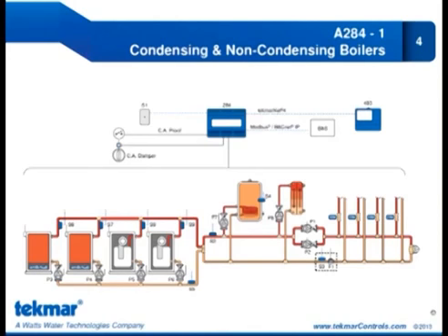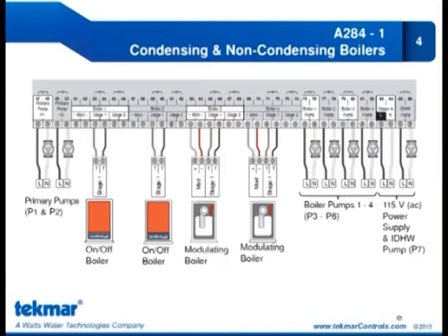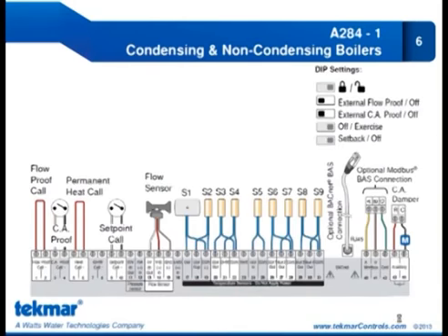You could then use the Tecmar stager function, where you select a switch in the 423, and then we have dedicated terminals which wire into terminal 16, EMS input, and 19, common. So the 423 provides a target temperature to the 284. We in turn interpret that as the target temperature and operate the plant to maintain that temperature. It's no different than what you do with a 423 with, say, a 275 or 274.